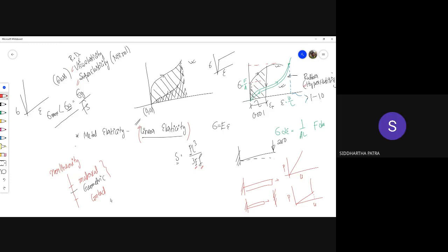The point is that with contact also the system behavior changes. By system behavior, I am strictly talking about the stiffness of the system, the instantaneous stiffness of the system. If that stiffness is going to be constant throughout, then it's a linear finite element method problem, which is the tiniest domain of the finite element method, but the most basic version of it as well.